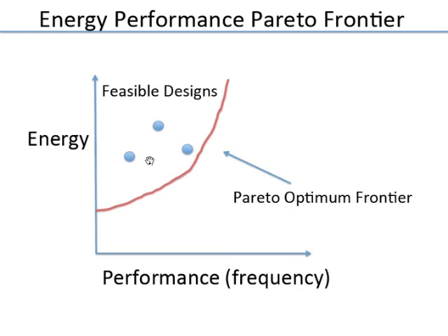So these are basically all the things we have been looking at so far, all the different techniques and so on. They all go towards getting you down to the optimal point. As I said, some of these things are discrete things you have to try out. There is no mathematical formula which will tell you, okay, do distributed arithmetic versus this. These are discrete choices, right? Whereas for something like energy versus voltage, we could have some formula. So it's a combination of all these things which describes the design space.